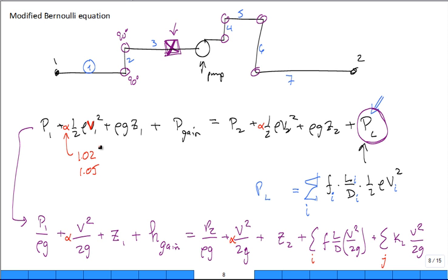But if it's laminar flow, guess what alpha is? Now, we just don't have a lot of cases where you have laminar flow. And if you do have laminar flow, guess what? The kinetic energy isn't all that important in laminar flow because it's slow-moving flow. And so the pressure terms are big, and maybe the rho g z terms are big, but typically this term is small.